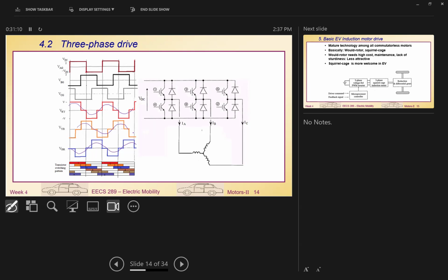So in all these integral drives, including your EV or your home inverter, or a grid-connected PV system, the inverter doesn't produce a pure sine wave unless they put in a filter. So when you buy an inverter, you need to specify whether it includes a filter. Some are called pure sine wave inverters, which means they include a filter to give you a pure sine wave. Some only give you this PWM.